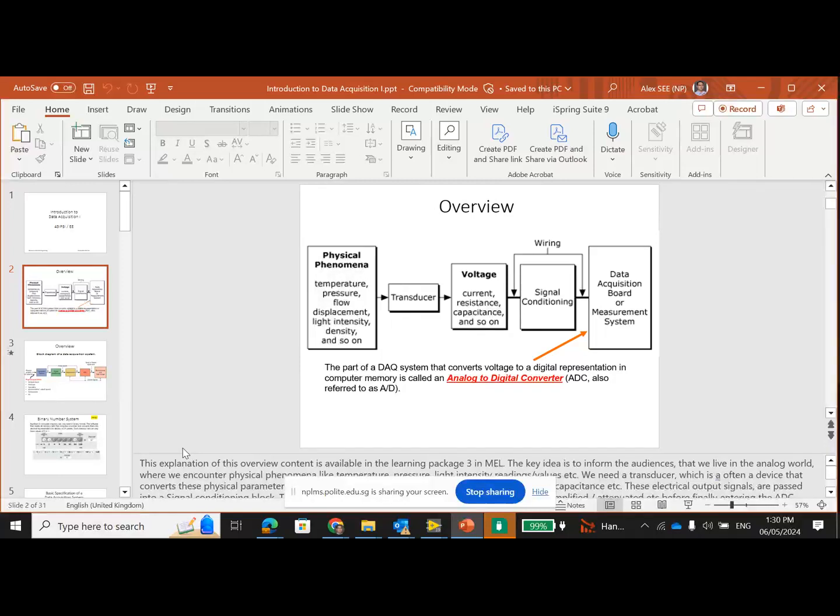If yours doesn't blink, that means that maybe your driver never installed. You should see a blinking green LED which is on this hardware. I want you to also examine this hardware. There's a National Instruments logo there, right? National Instruments is the company that makes this LabVIEW software and the hardware. And then it says it's an NI USB-6009. I don't know whether you can see that. So if you have it blinking, it's fine, it's good.